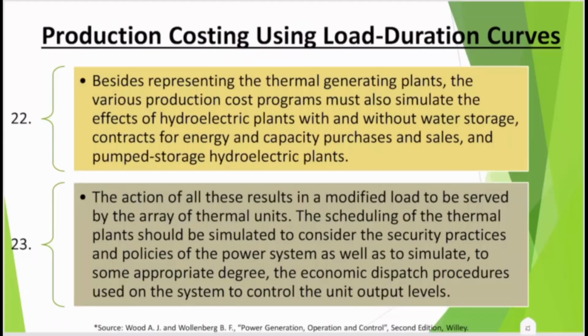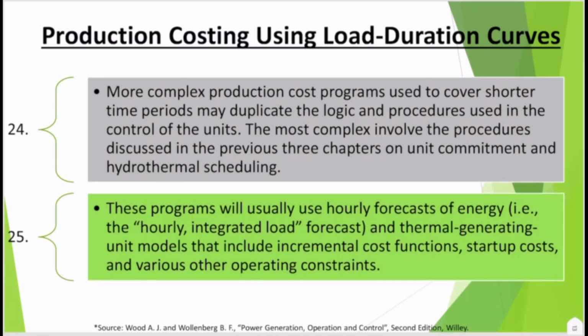The scheduling of the thermal plants should be simulated to consider the security practices and policies of the power system, as well as to simulate to some appropriate degree the economic dispatch procedures used on the system to control the unit output levels. More complex production cost programs used to cover shorter time periods may duplicate the logic and procedures used in the control of the unit.